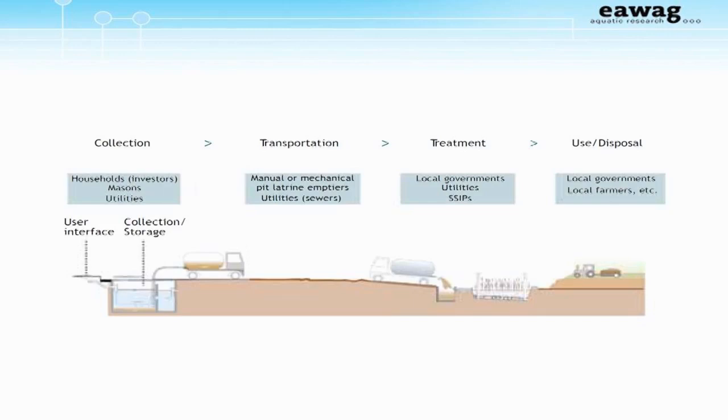Fecal sludge management includes the on-site containment of excreta, the collection and transport of fecal sludge, treatment, and safe disposal or end use as resource recovery. On-site or decentralized technologies can provide sustainable solutions in all areas of the world. Thinking all over the world has started to shift. Sewer-based solutions are effective, but are also very resource-intensive and expensive. Fecal sludge management can be considered a long-term viable option and possibly the more sustainable alternative compared to sewer-based systems, if the entire service chain is adequately managed.